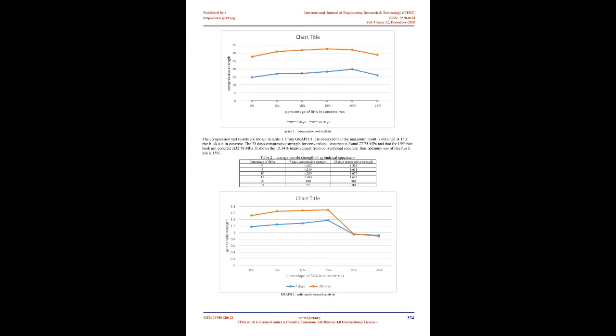4 Methodology. 4.1 Proportioning. The standard proportion according to IS 456-2000 for M20 grade concrete is 1:1.5:3. Here the proportion adopted is 1:1.80:3.283, which is determined by the mix design method. Cement is replaced with RHA at different rates, for example 0%, 5%, 10%, 15%, 20%, and 25%.